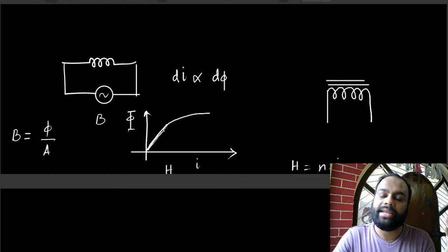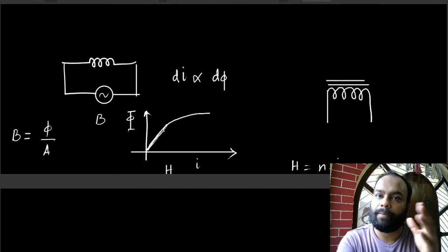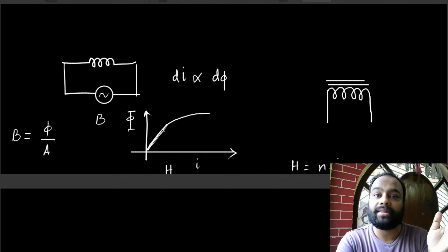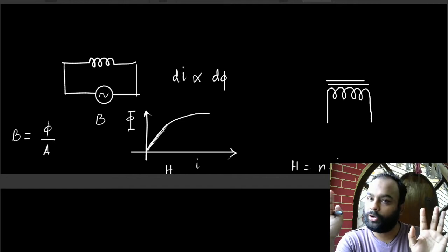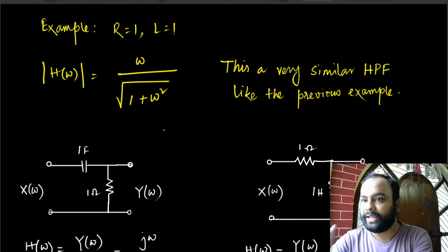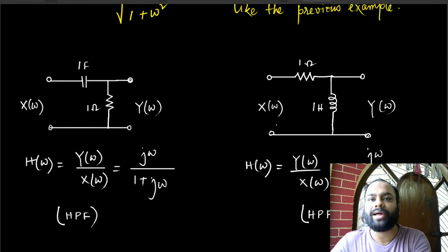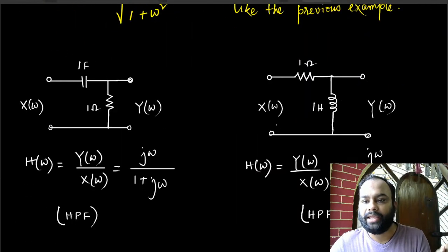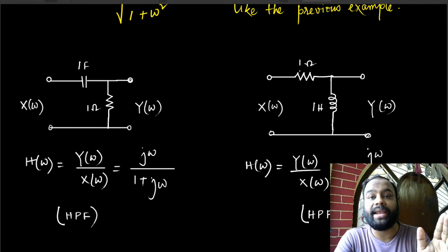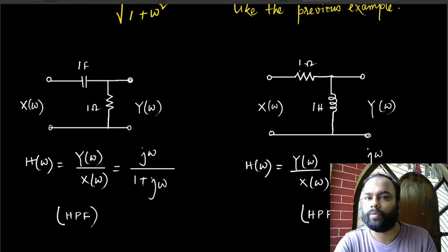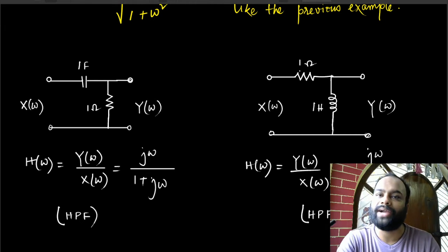As such, inductors are not linear beyond a certain point, but capacitors are far more linear than inductors. Do you get the point? The point is that here we are considering everything to be ideal. Here we are considering that this capacitor, this inductor, these resistors, they are carrying their linear time-invariant characteristics throughout every scenario. But in real life, that never happens.